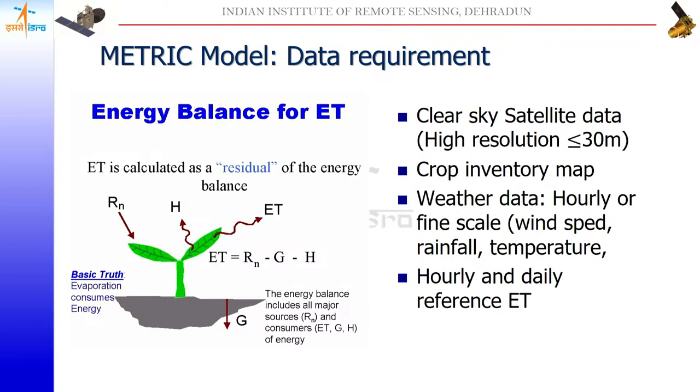But if you have high resolution data sets, for example Landsat 8 or 9, along with this, researchers in various parts of the globe are nowadays using UAV, unmanned aerial vehicle drone data sets, also for ET estimation using the thermal band data sets. Along with this, clear sky satellite data sets, crop inventory maps, weather data sets, and very precisely observed hourly as well as daily reference ET data sets are required in the METRIC model for ET.